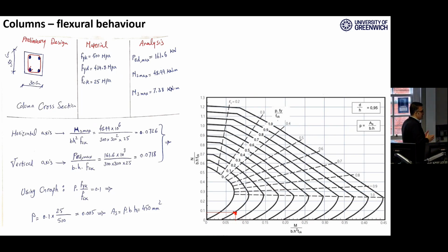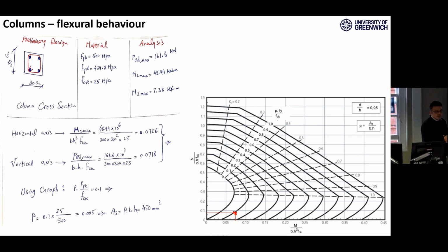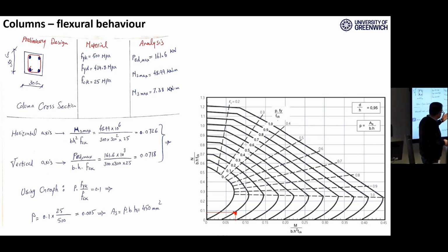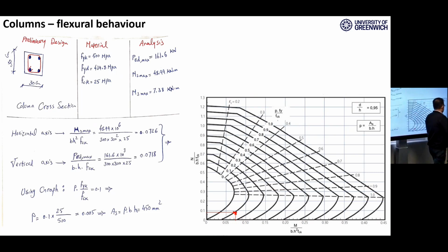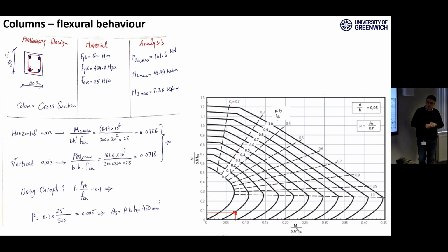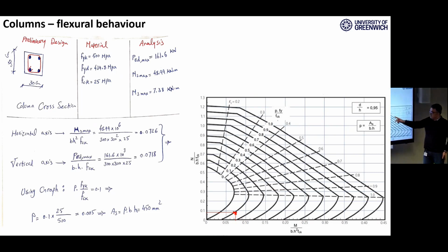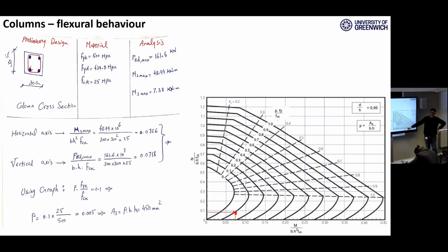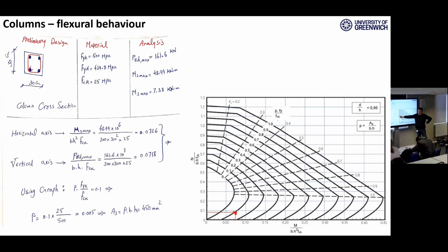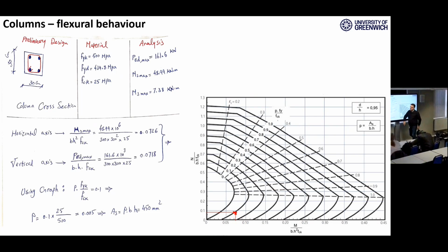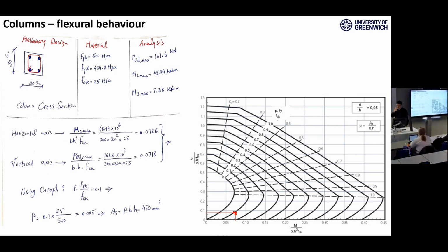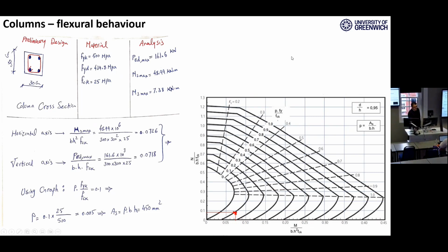When we came to the capacity of the concrete columns, we had some graphs like this. And for that one, every graph is for a specific column. Okay? And these two axes are the internal moment and the axial force, but normalized. Don't worry about the denominators, they are just normalized to be dimensionless.